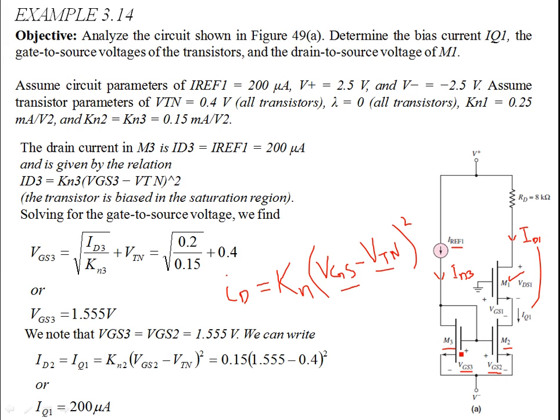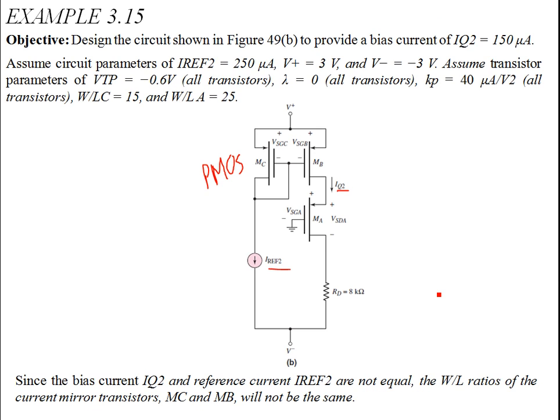The gates are tied together, and the sources are connected together over here. The VGS is the same, the conduction parameter is the same. So that means they both have the same drain to source current. So those are called current mirror MOSFETs. Here, in this example, let's read this out.